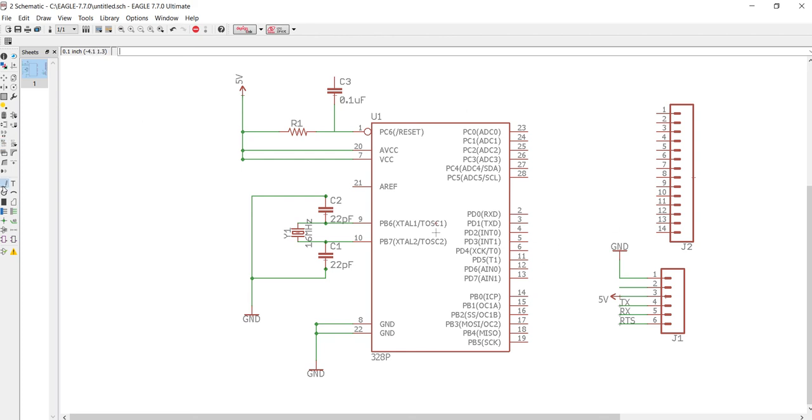And then if I do the same thing, let's say up here, add the label, double click, then type in name at the bar up here, hit enter, and then click on what you want to name, double click, and I'm going to type in RTS, and it should pop up with something asking if I want to join these. Do I want to connect them? Yes, I do.